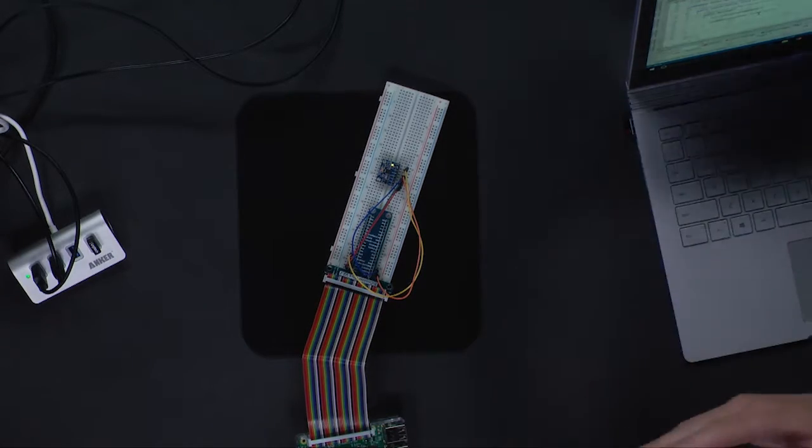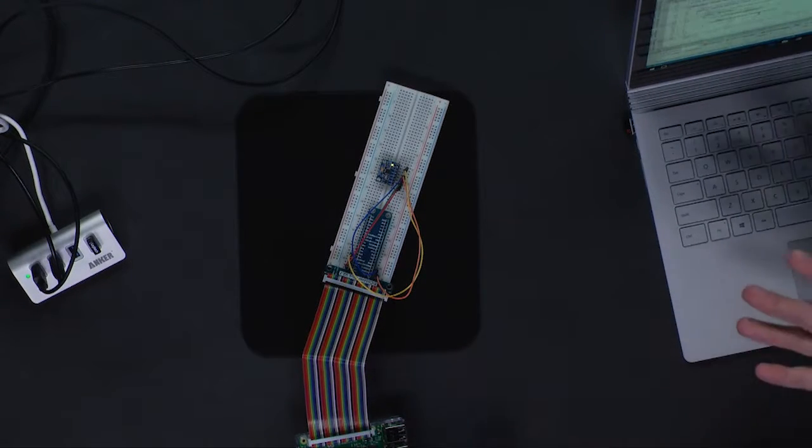Now, of course, there are some additions, though. Things that make it easier. That's why it's Android Things, not just Android. Exactly. Working with the real world, we have the peripheral I/O. So that's to access the general purpose I/O pins, which is primarily what those ribbon cables have to take care of on the Raspberry Pi. Input, output, those things that interact with sensors, servos, motors and things, the real world, as Adrian says. But there are also some APIs for those standard communication buses as well. So we've got I2C, SPI, et cetera. The standard things we're seeing in IoT, we've got an API surface for in Android Things.